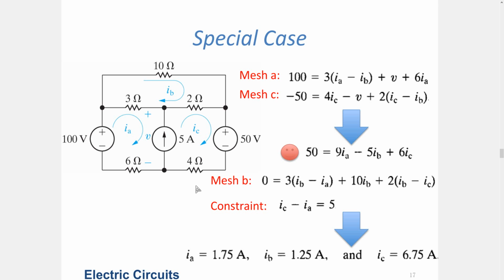You can connect it anywhere without affecting, or very little affecting, the circuit operation. As a result, once you know the node voltages, you can define the currents as the voltage difference divided by the equivalent resistance between the circuit nodes. So in practice, the node voltage method is more preferred and more useful.